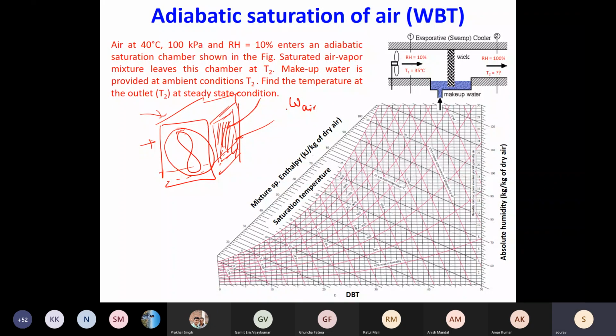So if your incoming air is already saturated and the air which will be close to this porous material will also be saturated, you will see that the potential is negligible or zero. It can be zero in places like Chennai, Mumbai, humid places. So there you cannot use the desert cooler. Whereas when it comes to Rajasthan, Delhi, there we have a very dry weather.